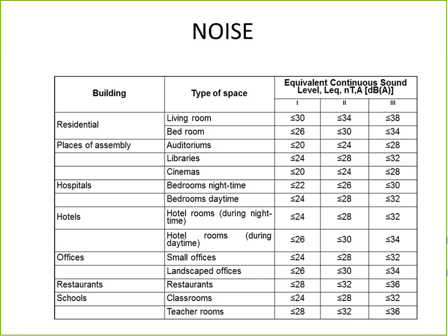You can say the noise does not directly influence the energy calculations or the energy use, but if you make a ventilation system that is too noisy, people will not use it, so we have to guarantee that. The other thing is, if you base your ventilation rate on natural ventilation and opening of windows, and you are in a very noisy area, again, that will not be acceptable to people. So we need also to look at the noise part.